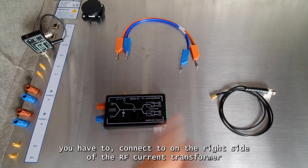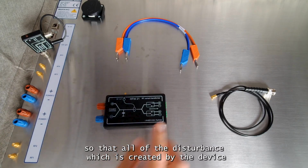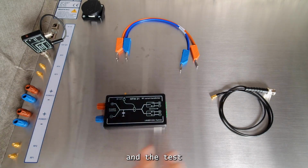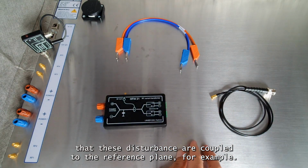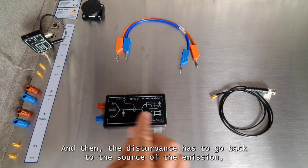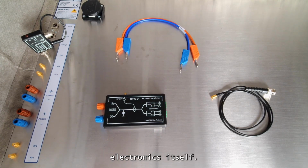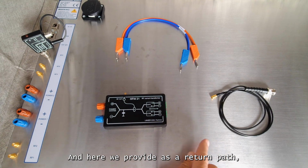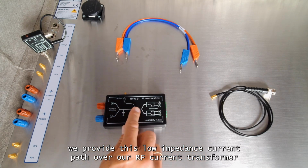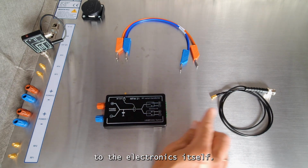The device under test you have to connect here on the right side of the RF current transformer, so that all of the disturbance which is created by the device under test is coupled to the reference plane, for example, and then the disturbance has to go back to the source of the emission, which is normally the electronic itself. And here we provide as a return path this low impedance current path over our RF current transformer, so that the current goes back this way over the power supply to the electronic itself.